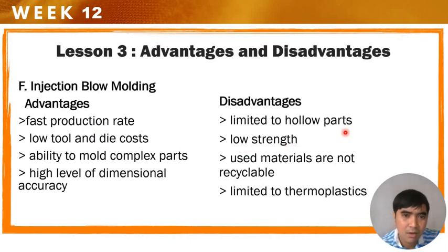Disadvantages: limited to hollow parts, low strength, used materials are not recyclable, limited to thermoplastics. So this disadvantage is it is limited to cylindrical products which have hollow parts, meaning the empty spaces inside. So those are the water containers and other liquid containers.